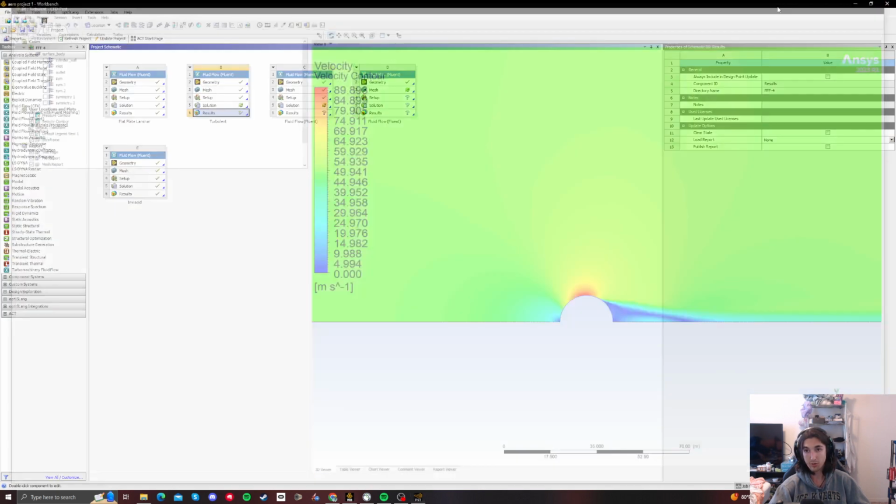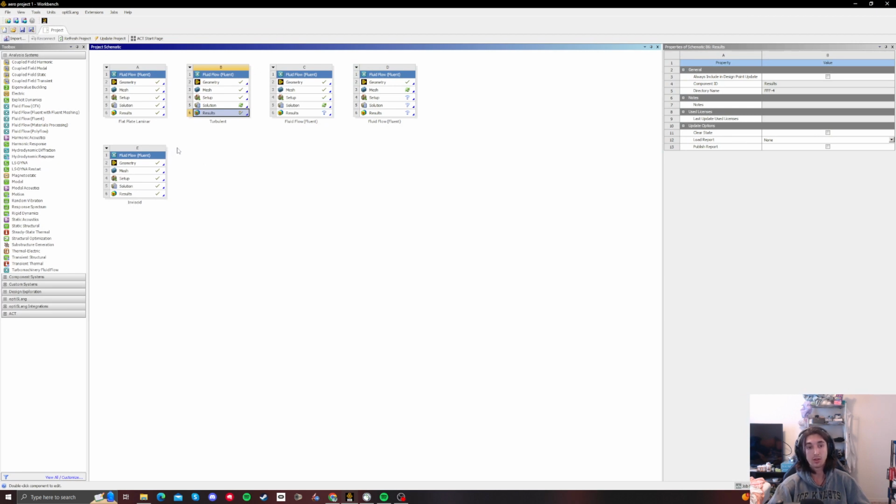I did have some meshing problems that made my thing not work so well. The easiest way to tell is to do your inviscid one first because it has to be symmetric, and it's very obvious when it's wrong. So if you have a meshing problem, it's not going to be symmetric and it's not going to look nice, and you just honestly start over. That's what I did. I had to do it twice. It's not the end of the world.